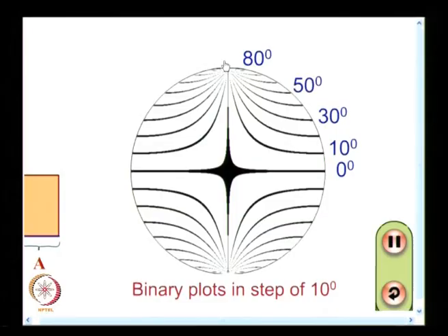In the case of Moire, I can get u displacement, I can get v displacement separately, and getting them separately is better. Though I have to do one more experiment, getting them separately in an optical arrangement is far better from processing point of view than getting the image of sigma 1 minus sigma 2 superimposed on the isoclinic pattern. That is what you have seen here.